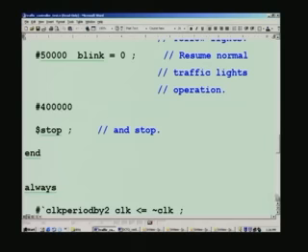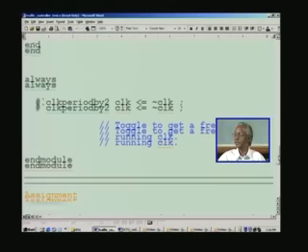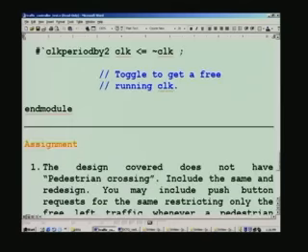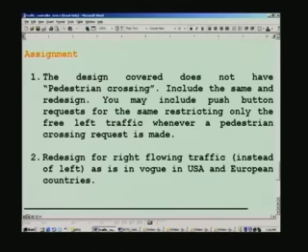This test bench is a very simple and straightforward thing which we have already seen. We run the clock by this statement, which is programmed for 10 right at the beginning of the code, and this toggles the variable called clock every 10 nanoseconds. That means 20 nanoseconds will be the time period, and hence 50 megahertz, which we have already listed earlier. This completes the test bench, and before we wind up we have, as usual, an assignment for you.